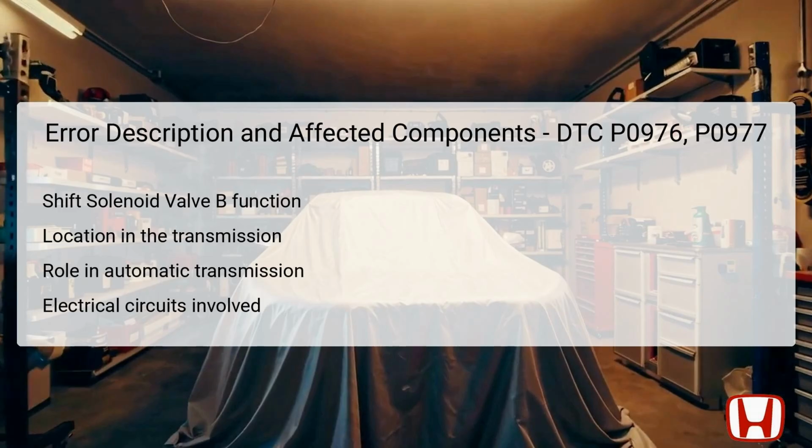If there is an issue with the electrical circuit, specifically low or high input signals, the transmission may experience performance issues or erratic shifting behavior. Therefore, recognizing the solenoid's function and location is crucial in addressing these DTCs effectively.